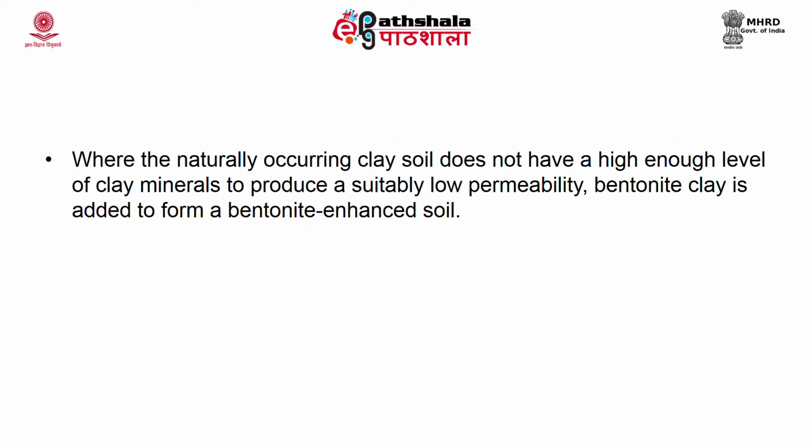Again, bentonite will be of two forms, sodium and calcium. Normally, sodium is used because it has lower permeability. Where the naturally occurring clay soil does not have a high enough level of clay minerals to produce a suitably low permeability, bentonite clay is added to form bentonite enhanced soil. I told you how a clay liner is produced, right.